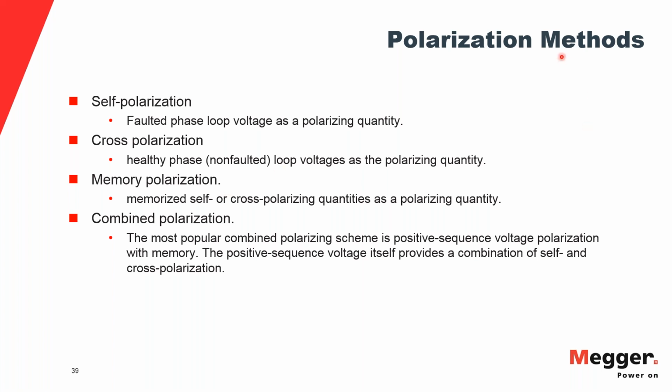You also have combined polarization. Now, the most popular one is using positive sequence voltage polarization. No matter how bad the voltages are, you can always calculate the sequence networks and then use the positive sequence voltage for polarization.